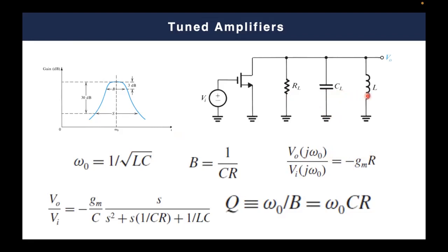Because at this resonance frequency, the impedance of the inductor, which if you remember from your circuit classes we call XL, is equalized by the impedance of the capacitance. At this point, XL equals negative XC. That's why the overall impedance of a parallel XL and XC is simply equal to 0. And this leads to what's called a resonance frequency.